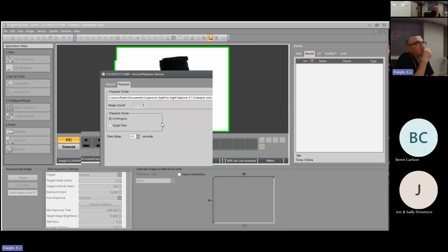The other thing you can do with glass though too, right? You don't have to use a vision system to do stuff. If I have a capacitive proximity sensor, versus an inductive proximity sensor, I have to have a metal part as the target. But in a capacitive proximity sensor, I could have wood, I could have glass, I could have plastic, and all of those would trigger that part. And so the leading edge of that piece of glass could trigger a capacitive proximity sensor, and I'd get a similar deal.